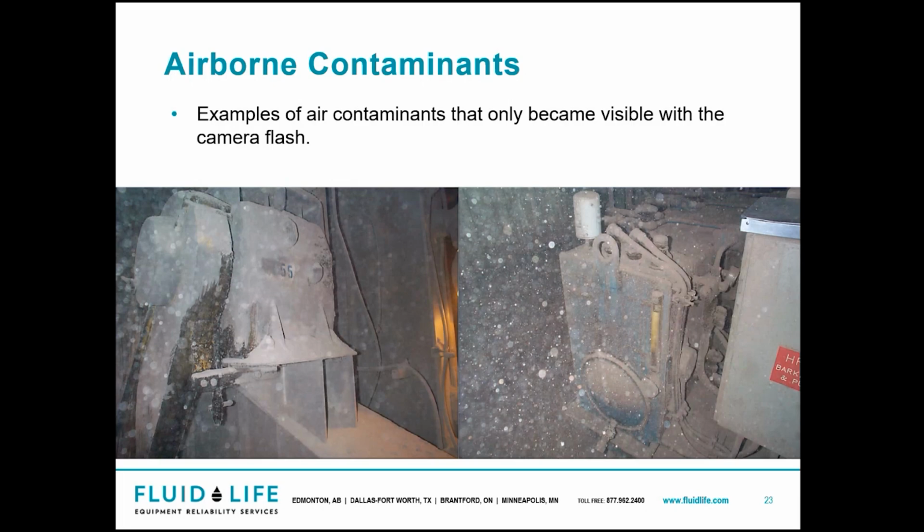What about when we see in certain plants, and those of you in this webinar who work in plant environments, if there's conveyors, how often is there something like a gearbox underneath the conveyor, and it's just covered in material, like it basically looks like a pile of product, and then there's really a gearbox under there. So you're kind of creating an insulating blanket on there, right? So what did I say about increased temperature on your oil, right? Where you're basically insulating it, you may be prematurely oxidizing that oil because it's getting warmer than it really needs to be.